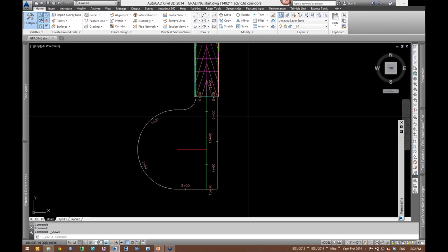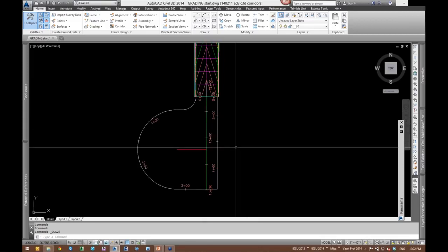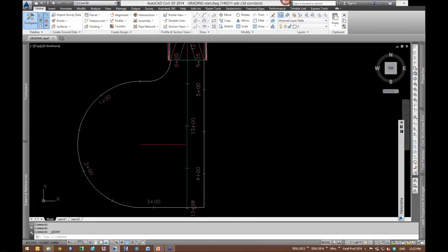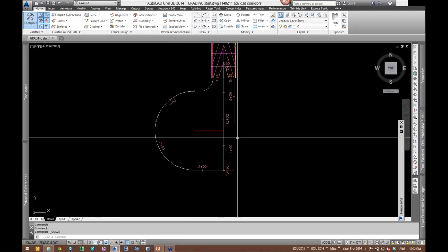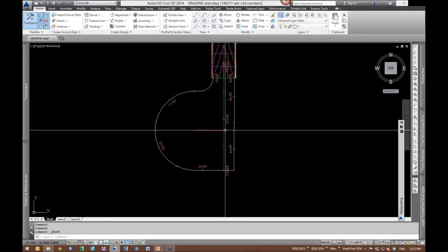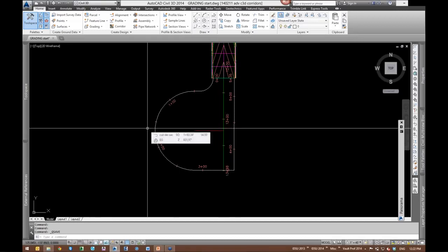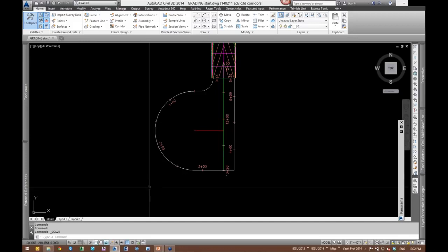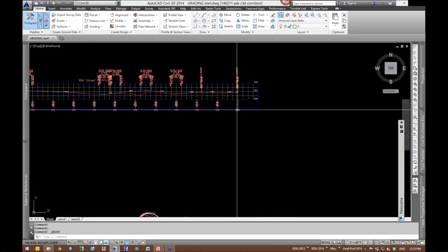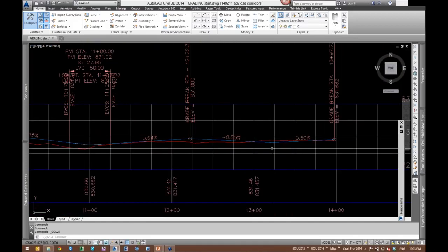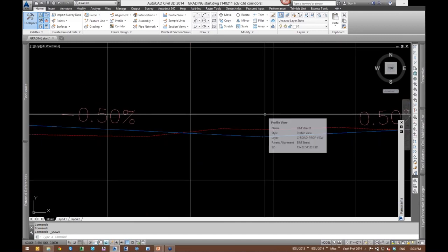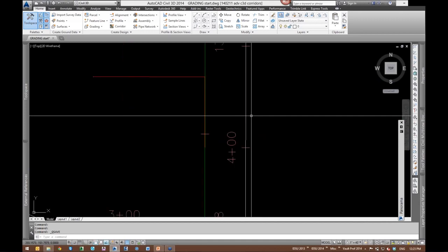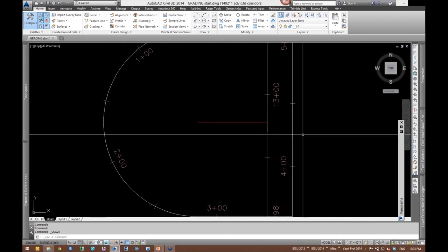All right, let's look at our auxiliary corridor. What does that need to be in this area? Well, what we're going to say is that the crown comes in here, and the crown just continues. So it's a 2% sheet drainage to the east, and then it's also 2% sheet drainage to the west. And if we look at the profile itself, the centerline profile, we actually have a low point right at the center of the bulb. Okay, so we're actually going to be draining to catch basins on both sides, one right over here and one over here.